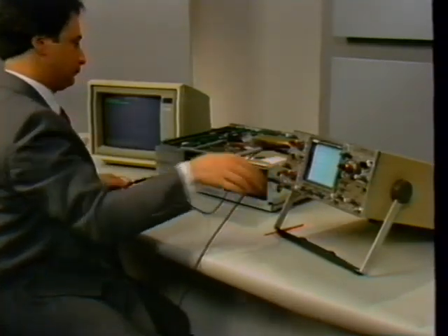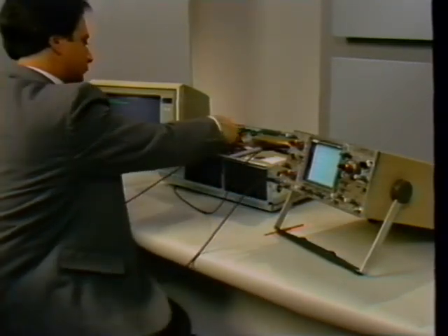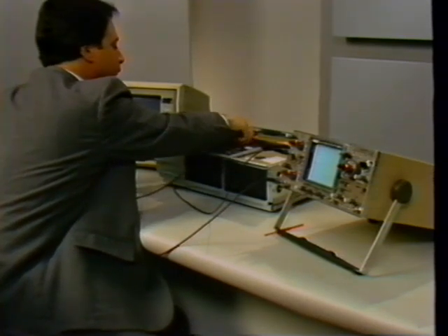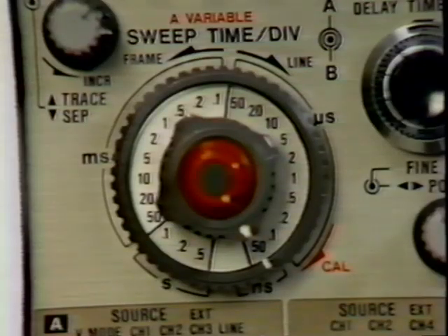Next, let's look at a clock signal. This signal has an amplitude of about 5 volts, so the vertical attenuation settings remain the same. The frequency of this clock is supposed to be 4.77 MHz. To calculate its period, we take the inverse of that value, or divide it into 1. This indicates a period of about 210 nanoseconds. To display 2 cycles of the waveform, we will select a time base of 50 nanoseconds per division.